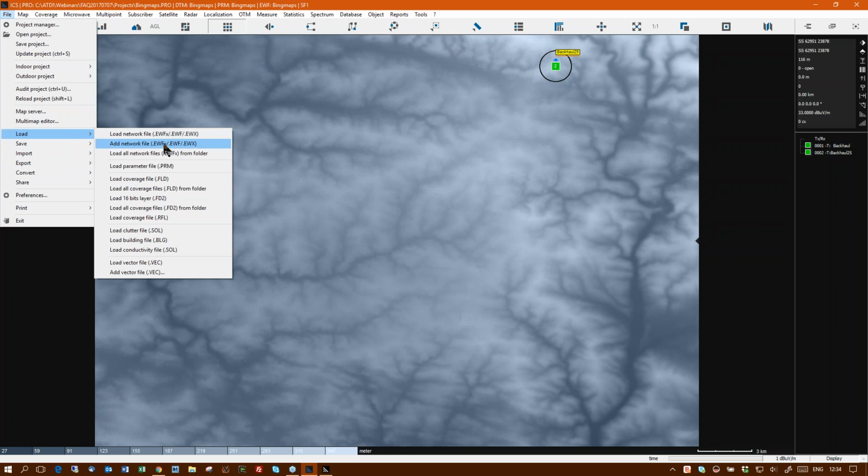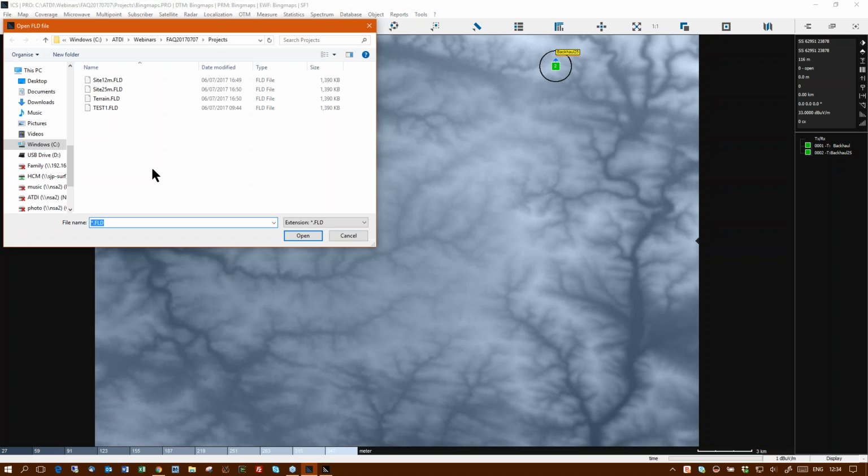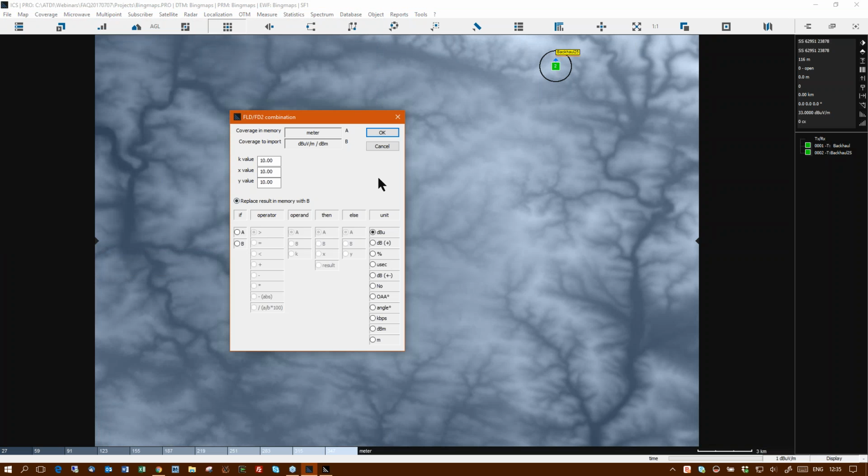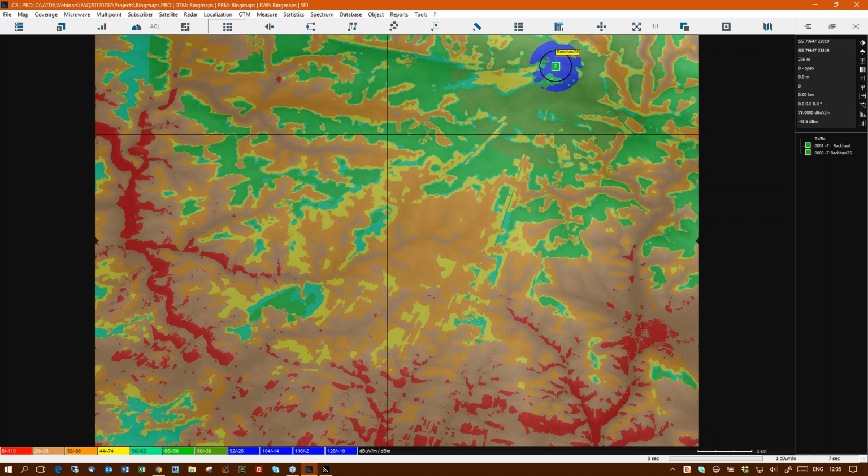Let's, for instance, load an FLD file for the 25 meter site. So this is the coverage for the site where the base station is 25 meters off the ground. This is at I think 22 gigs, which is why it's like this. This is effectively a 22 gig microwave link with an omnidirectional antenna, which is the easiest way to plan these things when you start.